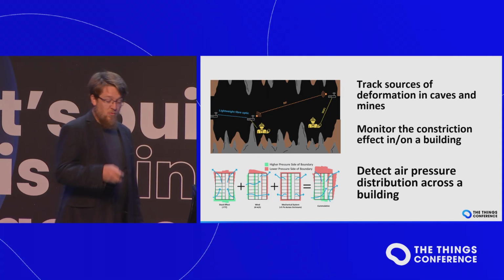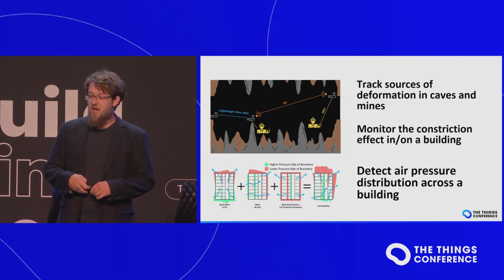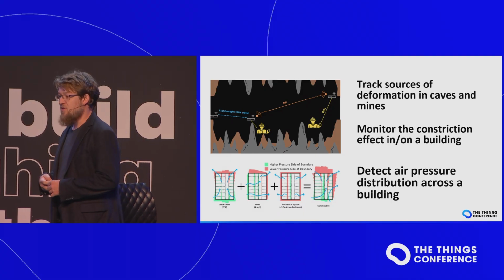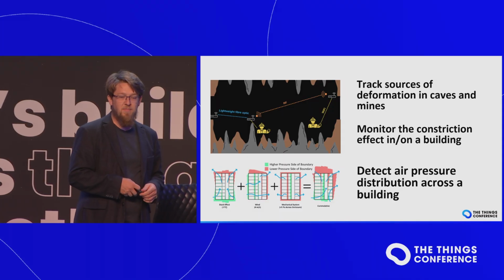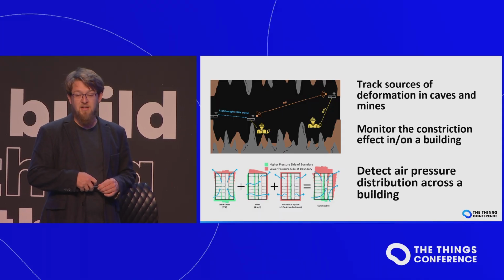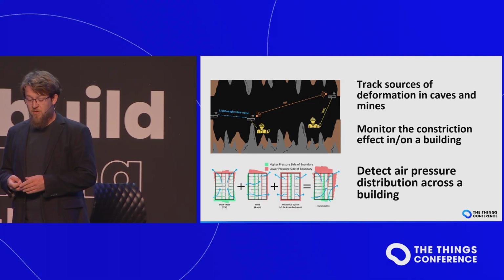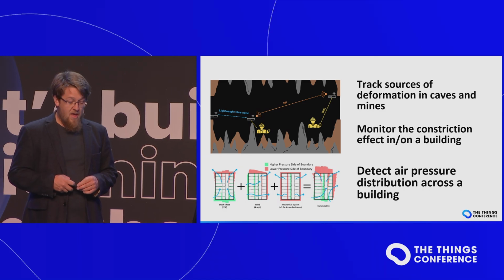And we go in further, so we go underground. For example, you have a mine or a tunnel or a cave. You want to have a large set of sensors there to see if the walls start moving, if the pillars start collapsing, or various kinds of things like that. And again, if you do that in a wired manner, it's pretty painful. Wirelessly, you can do it with LoRaWAN pretty well.